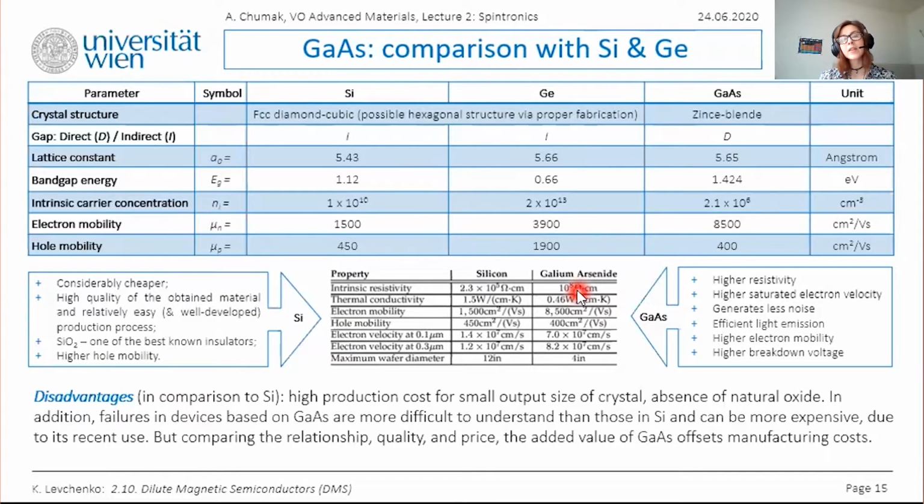When we are looking at the electronics for CMOS technology in particular, you have N-type and P-type transistors together that are forming logic gates. The currents through the N and P-type devices have to be balanced in order to have a well-functioning device. Otherwise, you will have jitters and time delays. And in order to balance the current, you need a decent balance of the electron and hole mobilities, because you will need to use the same proportion between these mobilities on gate widths in order to balance the